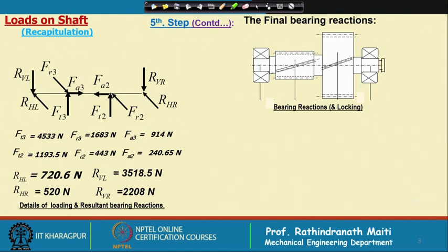After that we have considered the bearings. While we calculated the load, we estimated that bearing width will be within 25 millimeter, and from that we have found out the load point of the bearings. Now, after selection also we will arrange the bearing in such a way that it will remain the same. So, whatever load and bearing reaction has been calculated, we can accept for the next part.